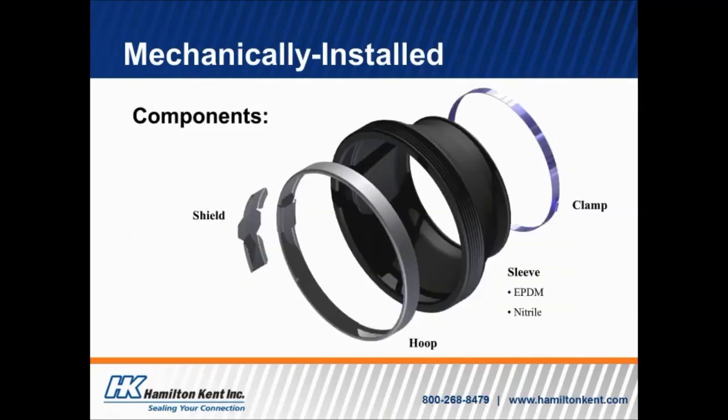So what are the components of a mechanically installed boot? You can see here that there are really just 4 components. Number one is the shield, over to the left-hand side. That usually runs underneath the hoop just to protect the sleeve portion of the boot from being cut or punctured by the hoop as it's being tightened.